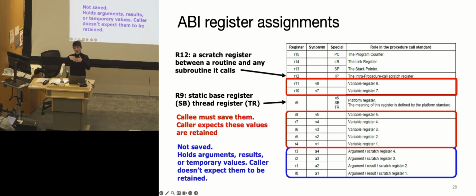And then when you pop, you pop R0, and then pop R1. When you push, you decrease the stack by 4 and then push it in, and then you decrease by 4 and push the second one. And when you pop, it's just the other way around. The order is always determined by the index number of the register, no matter how you put them. Any other questions?